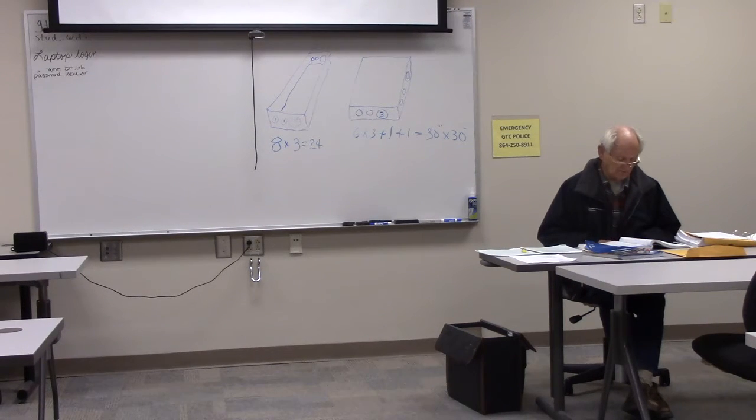The depth of a pull box with conduit runs entering at right angles. The depth now, we didn't discuss that, but maybe we should have. Need only be deep enough to permit the installation of locknuts and bushings.